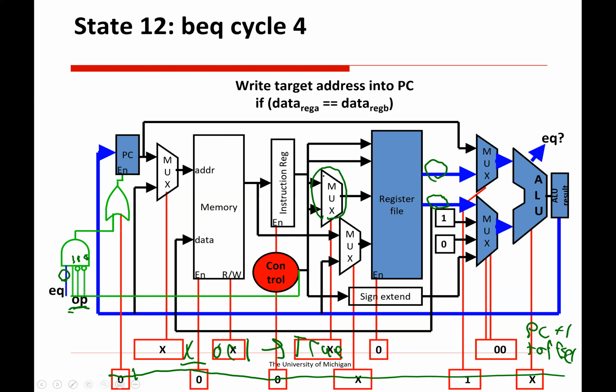So going left to right, it seems like, so PC, so yep, okay, so yeah, you're just looking at these. So yep, this is the PC, because sometimes we're using the PC to access memory when we're loading an instruction, and sometimes we're using the ALU result, which is the load and store address plus offset. That's going into that mux.